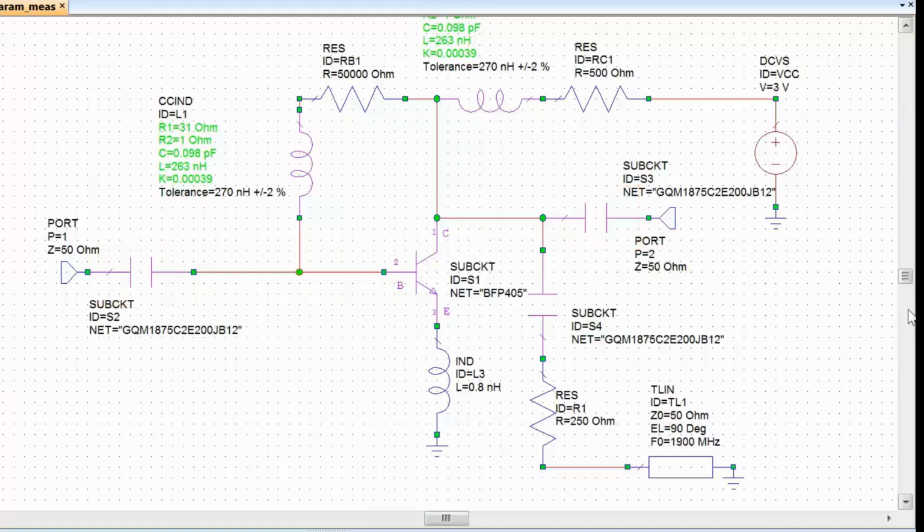Equally, we looked at how to avoid RF signals flowing back into our power supply by using RF chokes. And this avoided the bias being modulated and ripples being added onto the biasing voltages, which could create instability and oscillations and possibly ultimately damage the device.